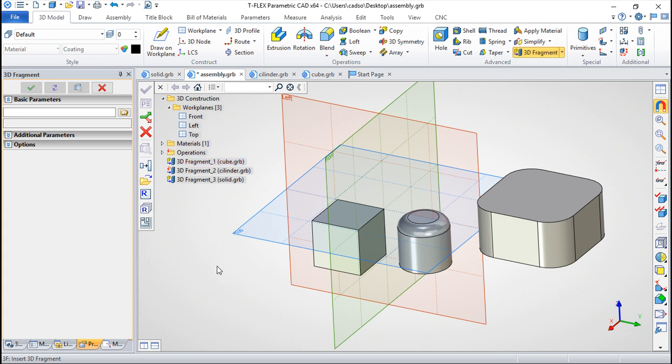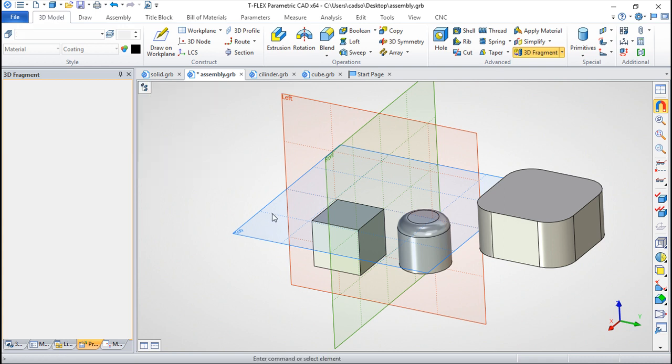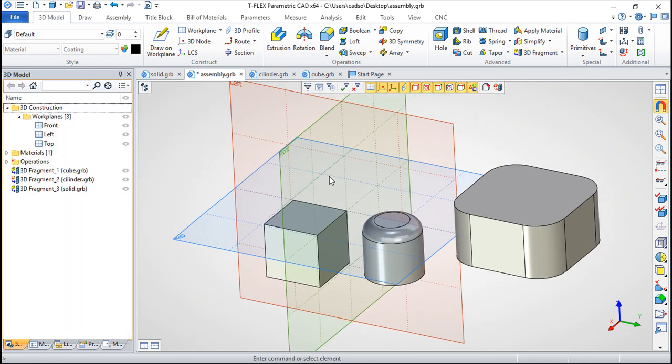Okay, and this is very interesting. So this is the concept of the bottom-up geometry. Besides, you can have another idea called the top-down design, and the top-down design will work directly in the assembly environment. And we can work on this in two ways. You can work with a top-down concept by saving already existing solids in a separate document.